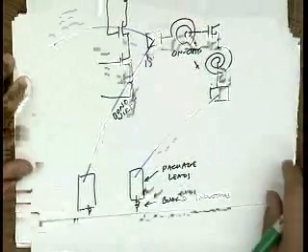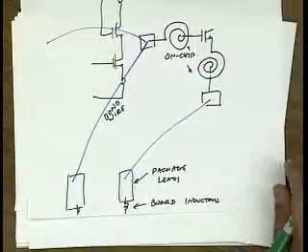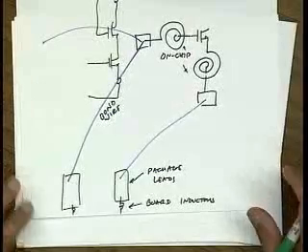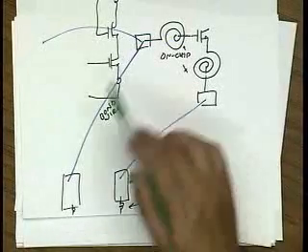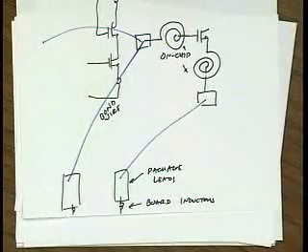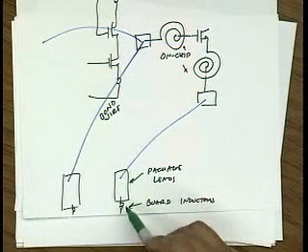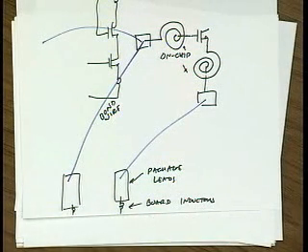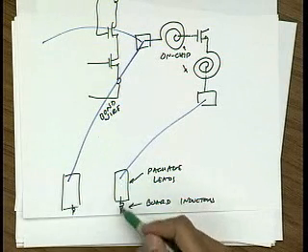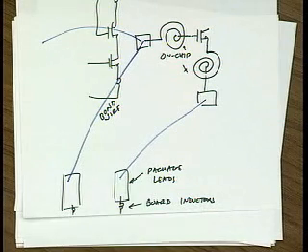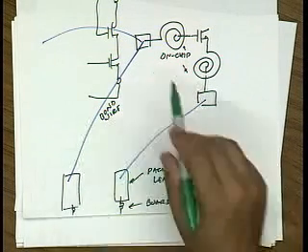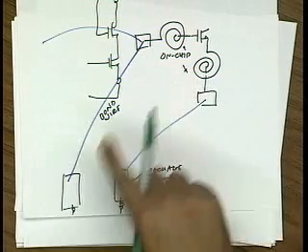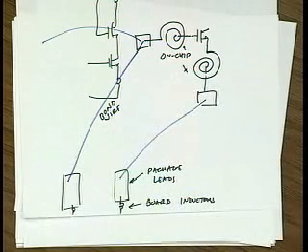Now from a design manufacturing perspective, this may seem a little bit like a nightmare, right? Because these bond wires can vary, their lengths can vary. For traces on the board, the amount of inductance you pick up can vary depending on the board height, the distance to the ground plane. Essentially on the board, the traces look like transmission lines if you do it right. And so this topology requires a lot of fine-tuning in order to get the matching right.